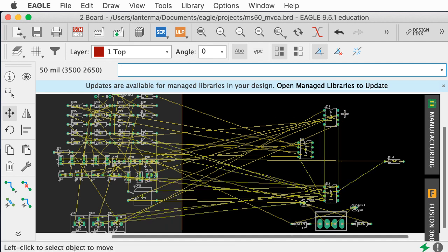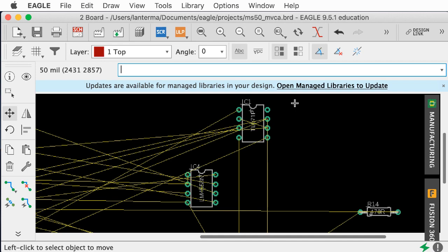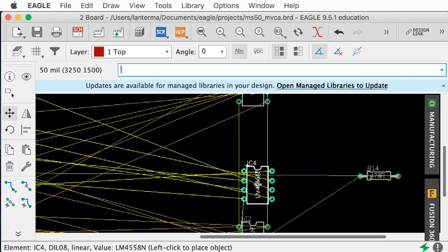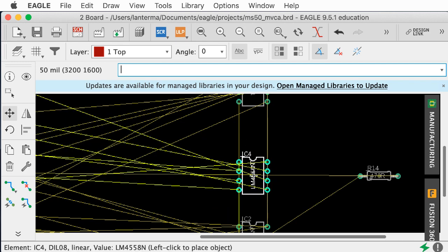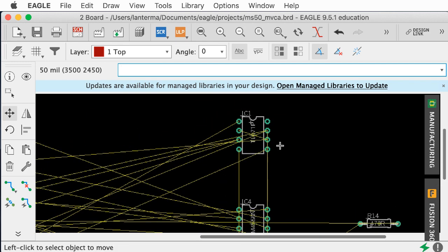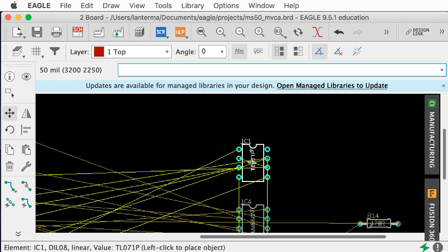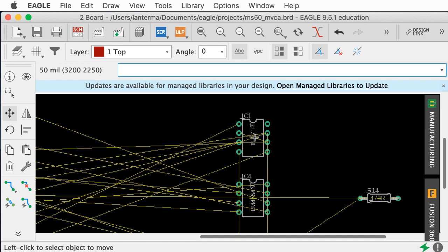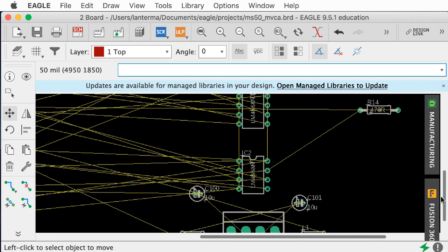And then if I look at the other 2 op amps, I know that one of them is associated with the inverter and the integrator. That's the 4558 here. It's used in both of those. And I know that the TL071, that just has to do with the integrator. So I'll put it up here by itself. All right, so I have those things.